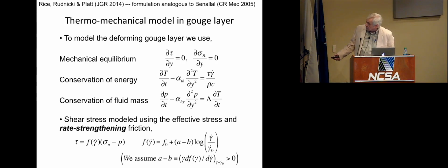And then in a related way, conservation of fluid mass has to be invoked. As you raise the temperature, the pore pressure rises just because the fluid wants to expand more than the host rock and it doesn't fit anymore. But as you create non-uniformities in pore pressure, that drives Darcy-like fluxes, and the divergence of that fluid flux balances out the conservation of fluid mass.